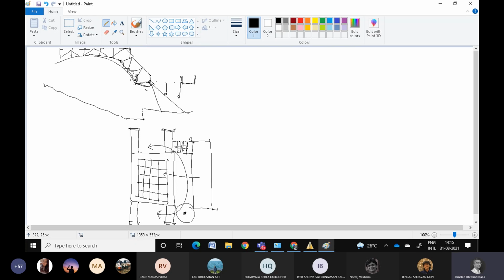So it's literally like a girder suspended below your existing girder. However, in plan, the catwalk will remain only in the areas where you actually expect to have the lights. So suppose you have lights here, your catwalk will be in a manner whereby you can walk along the catwalk and change these lights. So if I'm here, I should be in a position to stretch out my hands and change these lights that may be there.